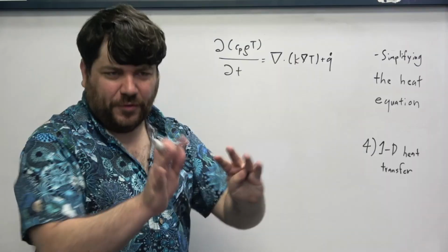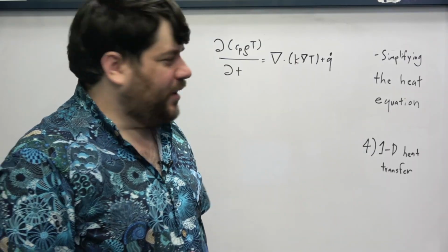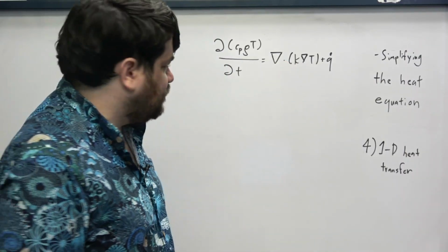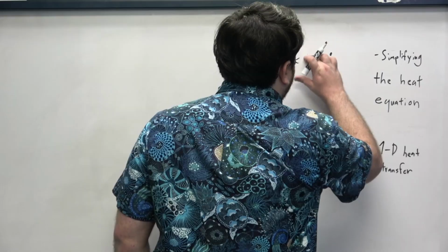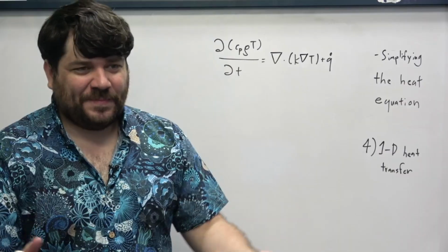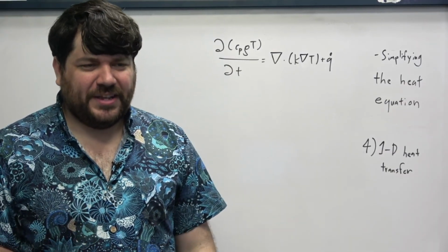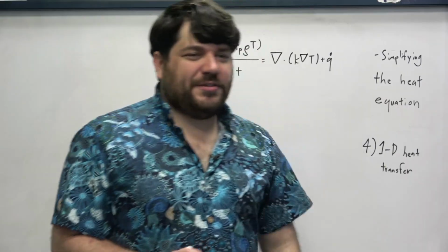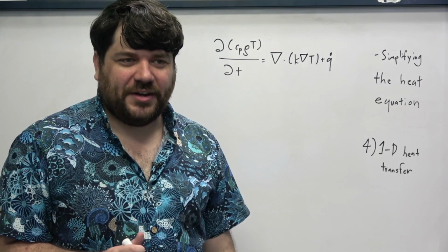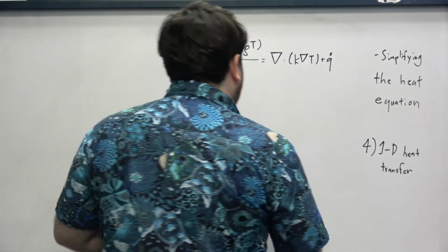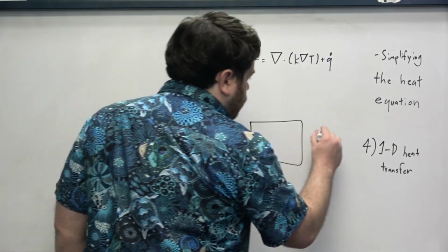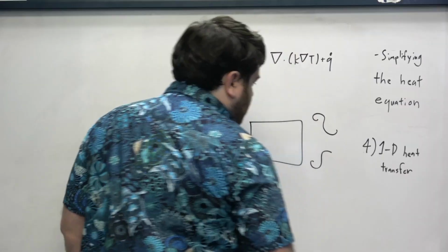This double derivative, or this goofy expression that's a function of second derivatives of the temperature field in space. And so what we really want to do is come up with some assumption that allows us to simplify what this is to make our lives a little bit easier. But this one-dimensional heat transfer assumption is still pretty valid. It still applies to a lot of systems that we work with in our day-to-day. So, for example, consider something we had seen before, the notion of a brick wall separating a room from an environment, right?